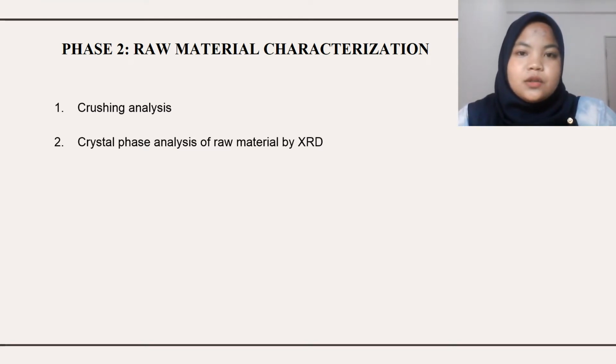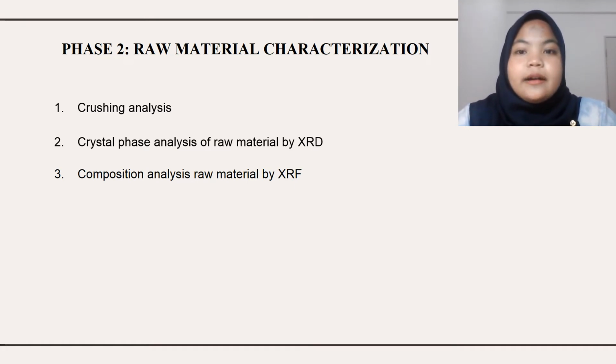The third is composition analysis of raw material by XRF, known as X-ray fluorescence. The non-destructive analytical technique XRF is used to determine the elemental makeup of material. XRF analysis detects the chemistry of a sample.